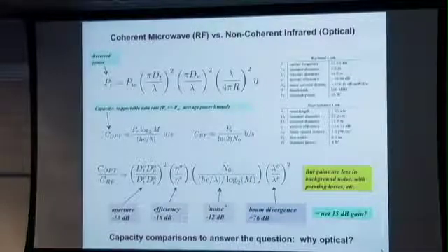And when you add up, taking into account you're using smaller actual apertures and have smaller efficiencies, the net is still a gain. But you can lose the gain with background noise, pointing losses, and other things that are very hard to do optically. So a lot of the engineering that's done in an optical system is to try to keep as much of the theoretical gain as you can. This isn't a maximum, this is a point design, but keep as much of the theoretical gain that you can get.